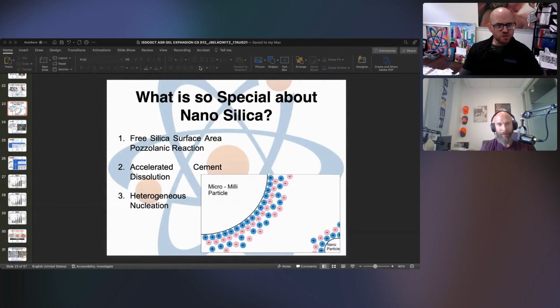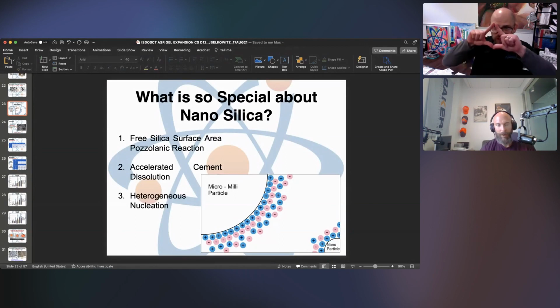Yeah, so there are a few things that we get from nanosilica, but it's also a nanoparticle. What you were talking about is something called particle-to-particle packing, right? That's a void filling thing where there are these really small spaces in between hydrated components of concrete that have water in them, and we can't get steel ball bearings into them.